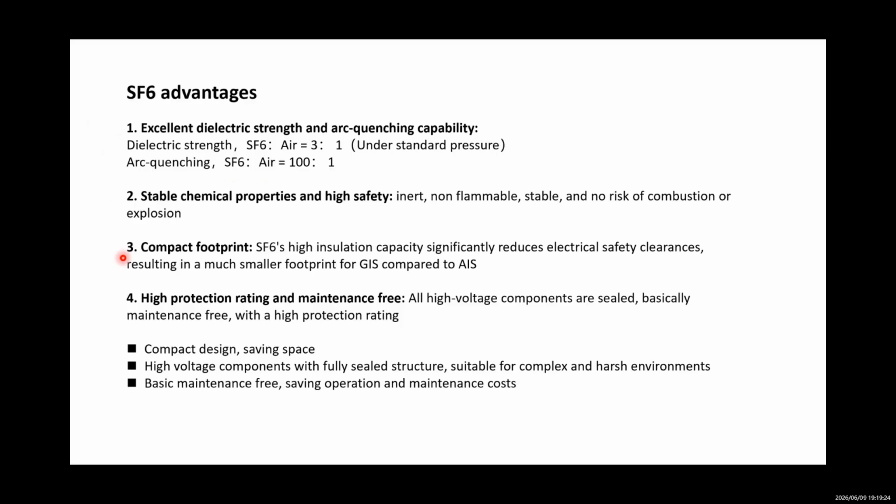Because of the high insulation capabilities, the electrical design is easier and the switchgear more compact. It reduces the electrical safety clearance, resulting in a much smaller footprint for GIS compared to AIS.